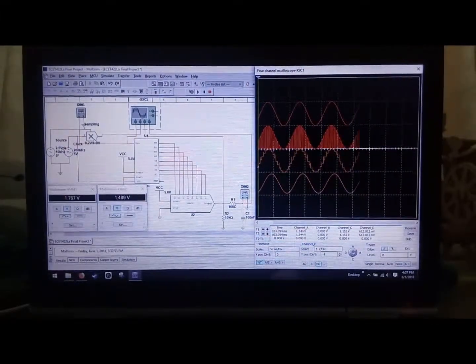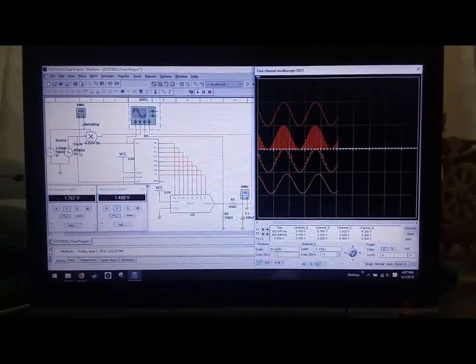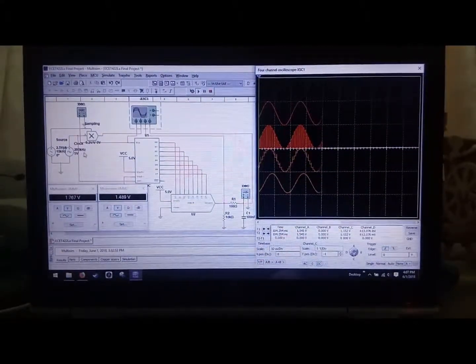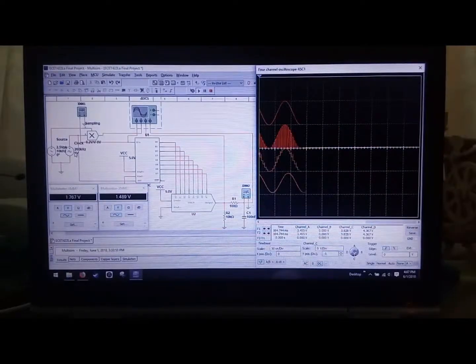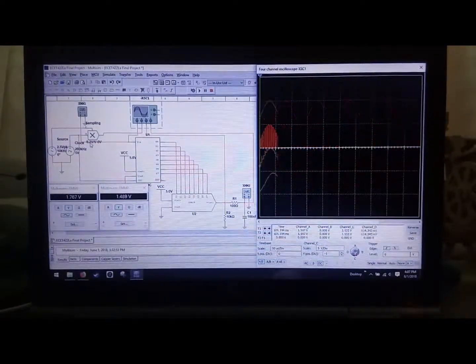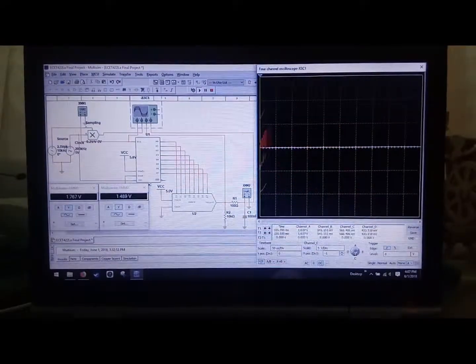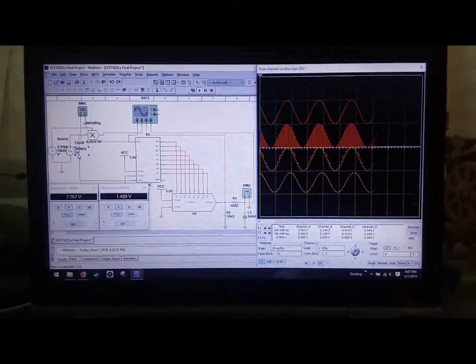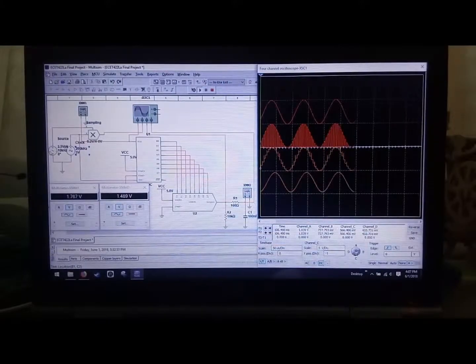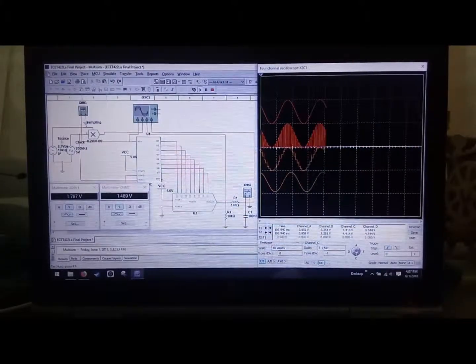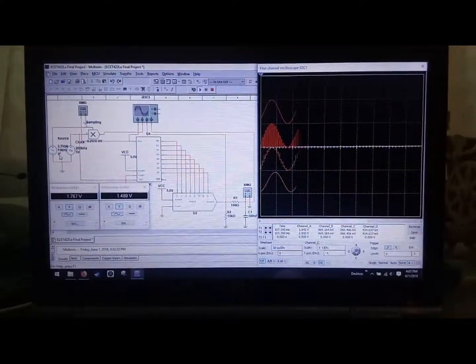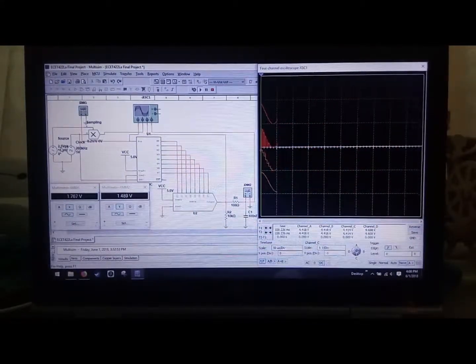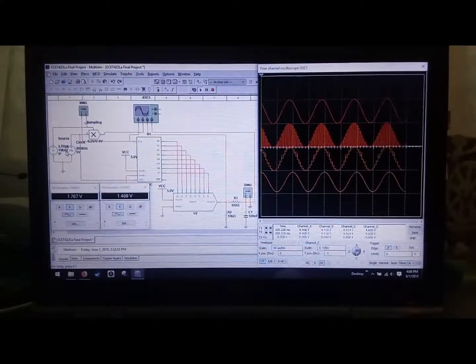The sampling circuit consists of a clock in which a very high frequency pulse is being outputted through a clock with a voltage peak of 5 volts. The next one is the source. Our source stands for the input signal, in this case 2.5 volts, 10 kHz.